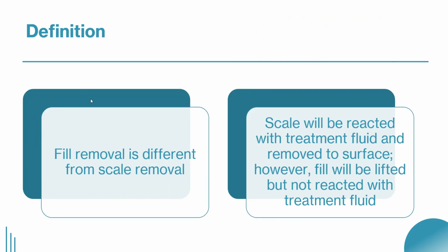And always consider that fill removal is totally different from scale removal. In scale removal operation, the scale is reacting with the treatment fluid. The scale will be reacted and removed to surface. However, in fill operation, the fill will not be reacted or dissolved and will be lifted to surface as it is. So in scale removal operation, you will dissolve and react with the treatment fluids. However, in fill removal, the whole particles will be lifted to surface as they are. So this is fill removal.